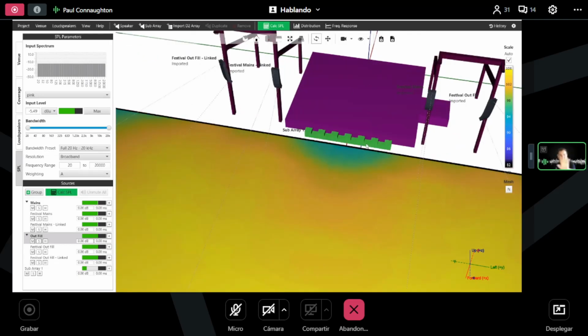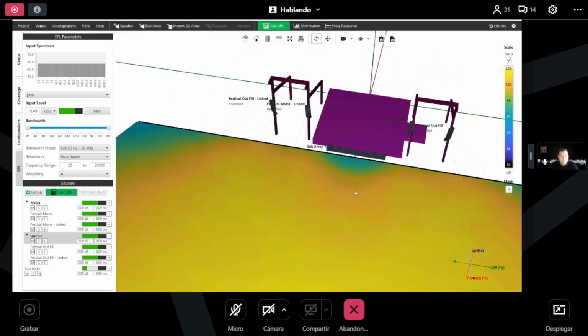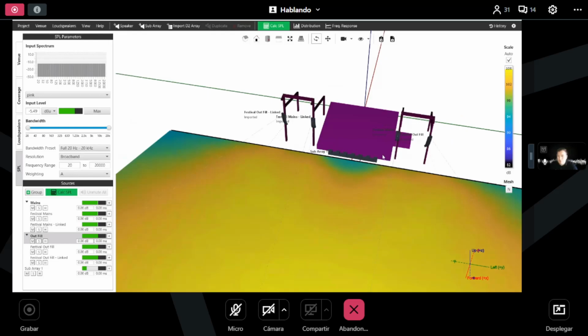So they're not stood right in front of the stage looking at somebody with the acoustic source coming from above their head. It's coming from in front of them where the source is, where the person on stage is performing that instrument. So what we need to do now is get some coverage in the near field. So we're going to deploy some front fill and help us to improve our coverage further.